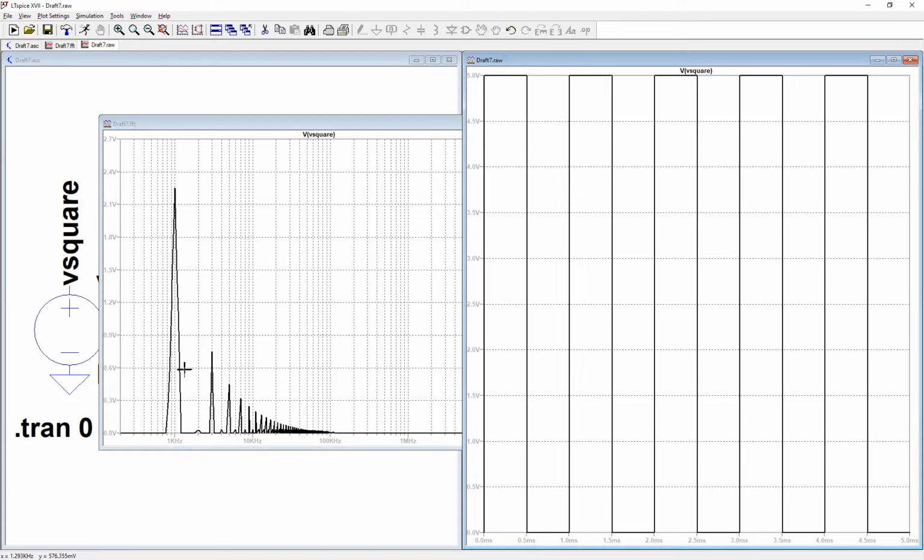Again, the spectrum I'm expecting to see here is a bunch of lines, where each line represents a harmonic of the signal. However, here I see triangles, and the reason is that my signal is not actually an ideal periodic signal, because it's just 5 periods. An ideal periodic signal instead has infinite periods, okay?